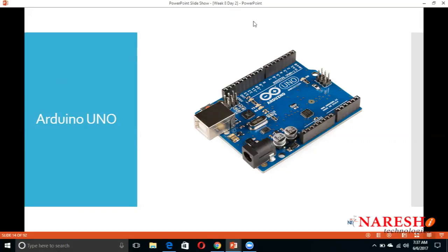If you are using any other platform or programming language, then first you have to program it, then convert it into a hex file, and then use the external programmer, this external programmer module, and interface it with these pins. Then you can directly upload the program inside the microcontroller.